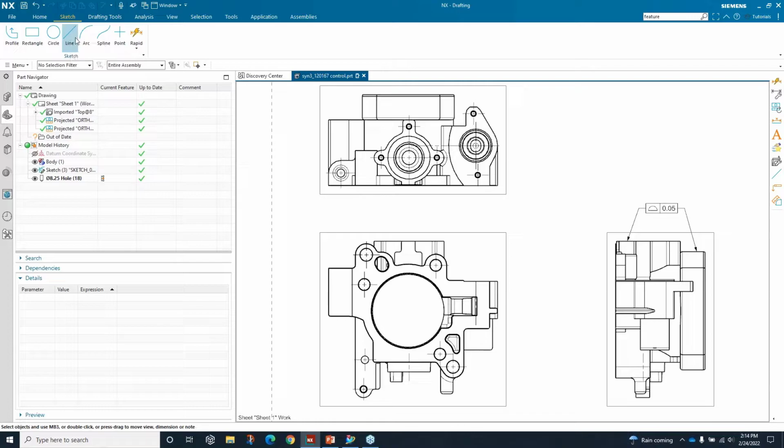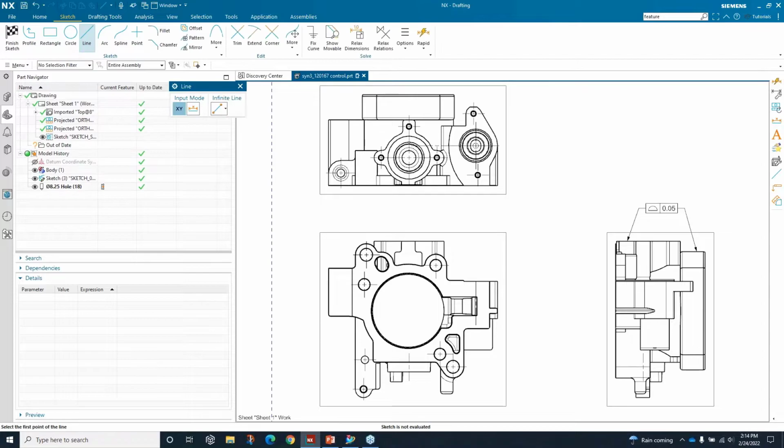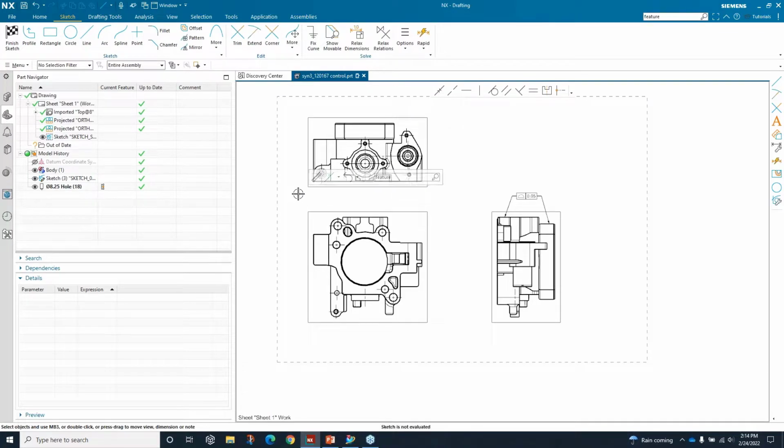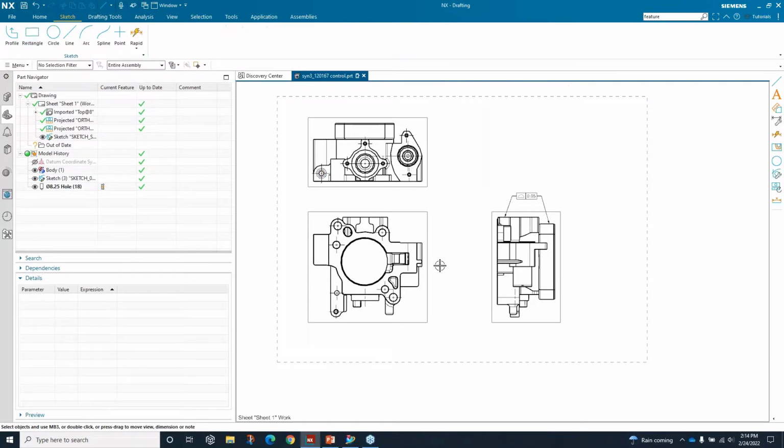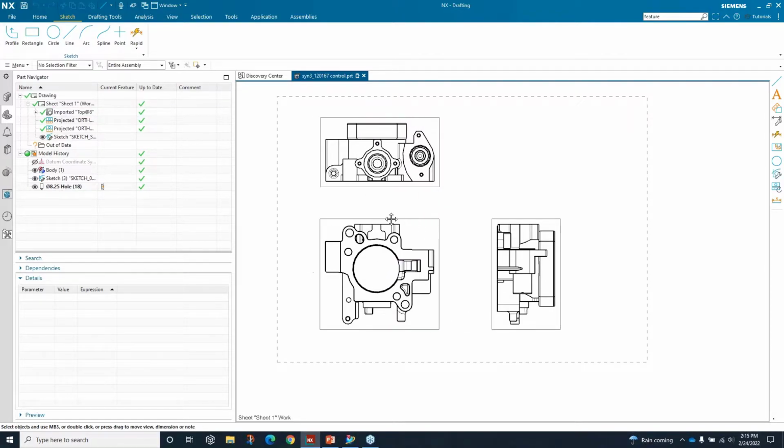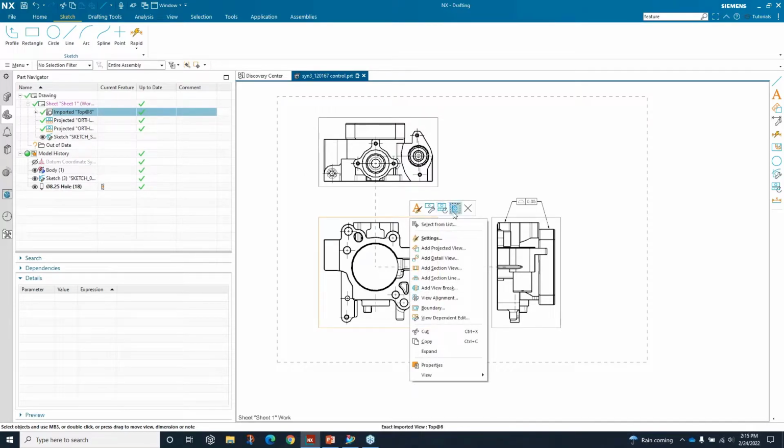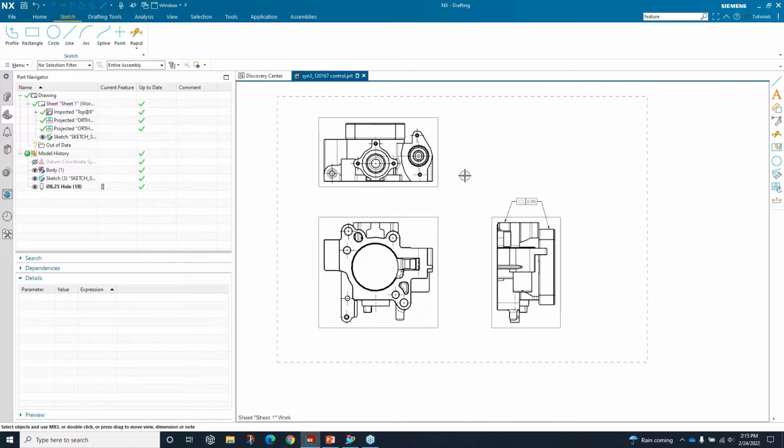Now here's just an example. I'm going to draw a line again, and just keep your eye on the border. So hopefully you can see it's blue. It's just helping us to see where the sketch is actually going to go. So some of our customers, they have it where they're drawing some reference sketches on the actual sheet, but then they're going into the view, and the problem is they couldn't do this. So right click, active sketch view.